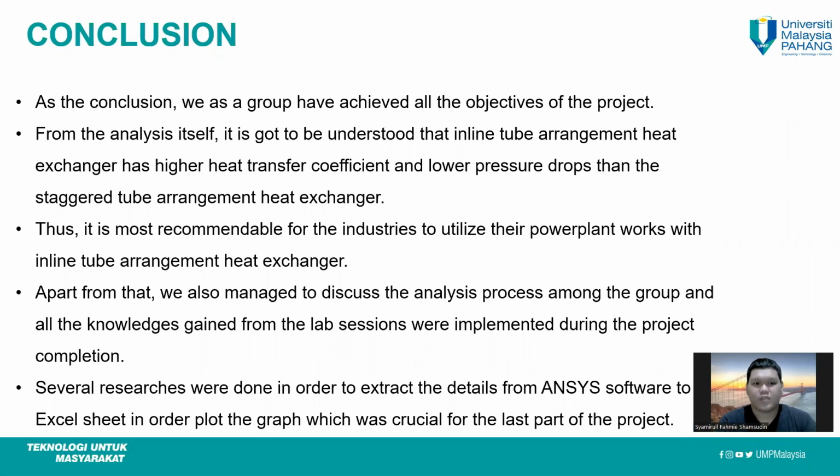As the conclusion, we as a group have achieved all the objectives of the project. From the analysis itself, it can be understood that the inline tube arrangement heat exchanger has higher heat transfer coefficients and lower pressure drops than the staggered tube arrangement heat exchanger. Thus, it is highly recommended for the industry to utilize inline tube arrangement heat exchangers in their power plants.